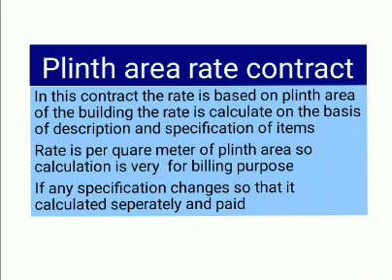In this type of contract, the payment method is divided in percentage of work, like on completion of foundation, the owner pays the contractor about 25%, and on completion up to lintel level, the owner, or we can say the client, pays 15%, and so on. So this is the simplest type of contract which is generally used in small projects.